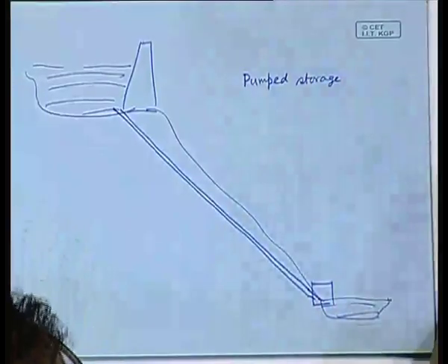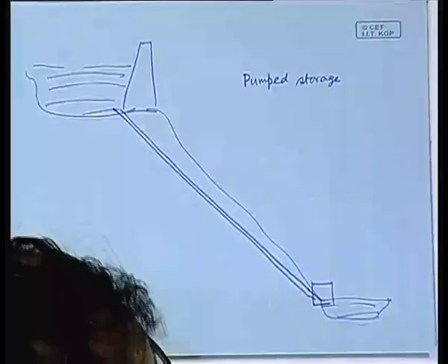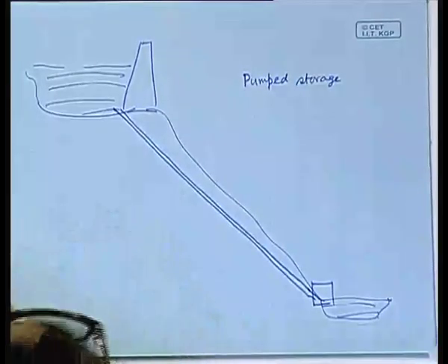Pumped energy storage. In many countries these systems are there, especially where you have a hydroelectric power plant. It really takes very little in addition to create a pump storage plant, because all that you need is that the same turbine should also be able to work as a pump, and most turbines are of that type. So a fan type turbine, for example, just imagine a fan type turbine, you allow water through, it rotates and it generates power. You put in the power and rotate it, it pushes water through, it acts as a pump.